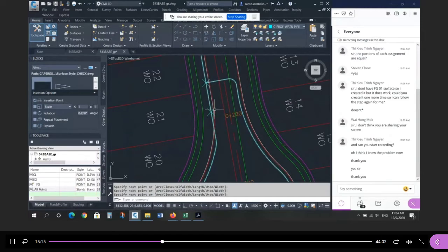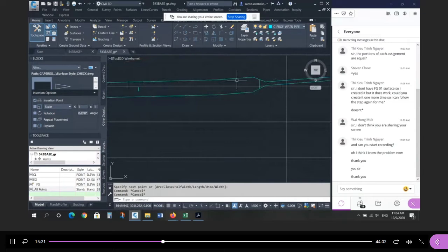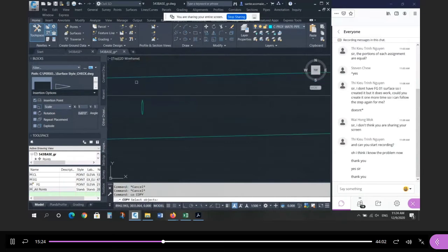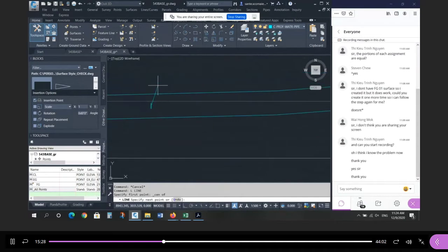So everything behind the water main should be hidden, so we can show it as a hidden line if you're talking about real drafting, right? So then I can make a copy of, I'm going to draw that back center. Just want to do this so I have a reference point. Extend here, and then trim it.